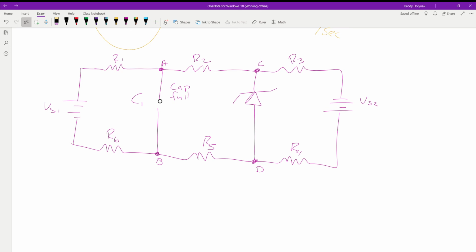Okay, what else do we have in the circuit? A Zener diode. So in the directions, we're given a VZ. We'll just say it's a 3-volt Zener. The next step we have to do is determine this diode. Is it in forward or reverse bias?